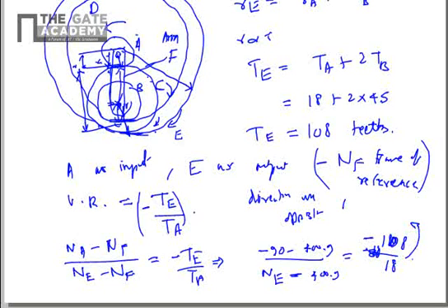So simplifying this equation, we'll get the final solution as NE is equal to 482.7 RPM, and this is a positive value, so it will be clockwise positive. So this is the answer for part 2. If you just look at the values of the speeds, you can see here this 482 and then 400.9, input is 90.